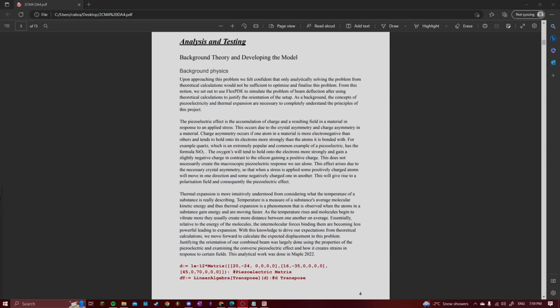In response to thermal expansion, the polymer is going to grow larger, thus shrinking the piezoelectric longitudinally such that it contracts in on itself. This is going to cause the beam to bend downwards if we have the polymer on top, which is what we want so that gravity aids the displacement as opposed to working against the motion. So we're going to leave the polymer on top due to that.